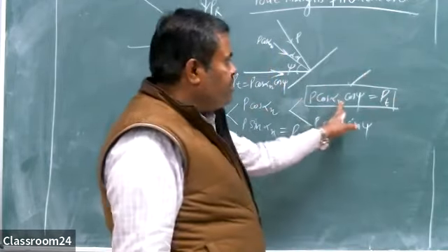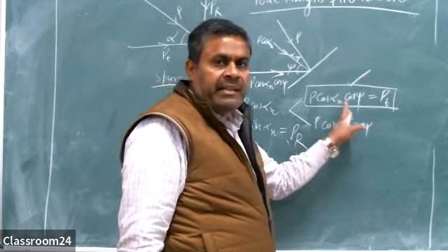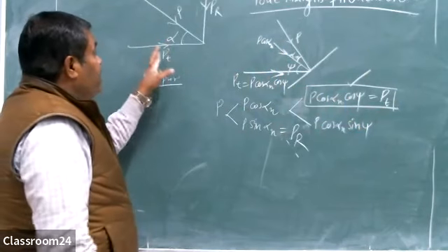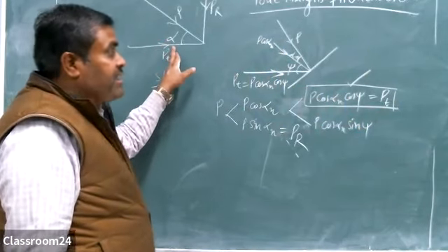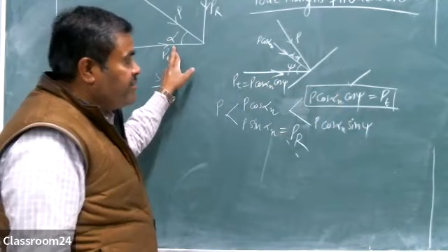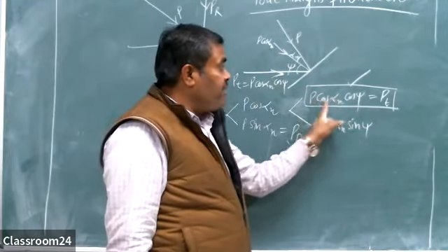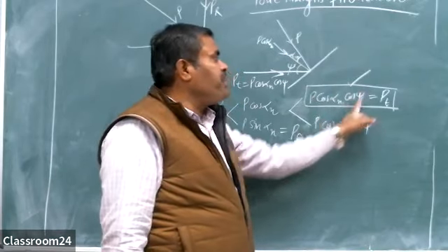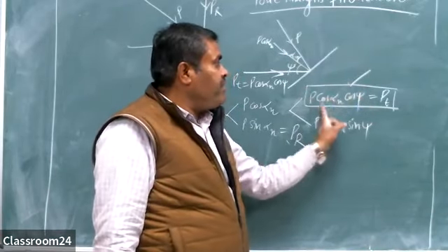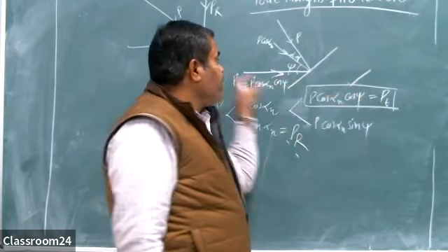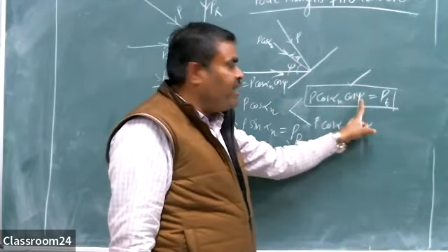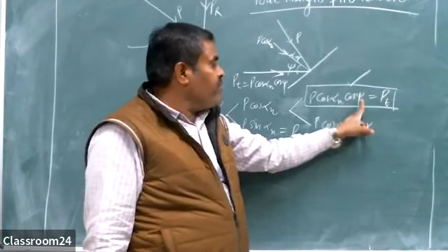This force is responsible for the bending failure of the helical teeth. In case of spur gear, P cos alpha is responsible for bending failure of the teeth, but in case of helical, it is P cos alpha and cos psi. This is the PT, and it will come into the calculations and the numericals. We have to find this PT. PT is dependent on the pressure angle and also on the inclined angle of the teeth.